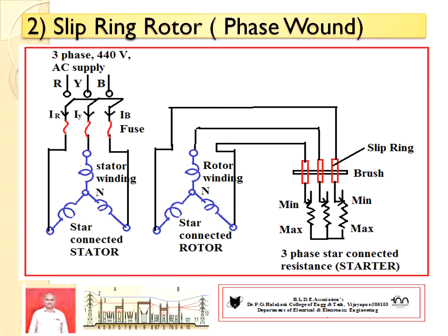Maximum, medium, minimum positions. Different speeds are possible. Once the motor runs at its rated speed, 3 slip rings have been shorted by pushing some metal collar arrangement on the shaft. Hence the motor runs at its rated speed. Before starting every time, we have to take this starting arrangement.